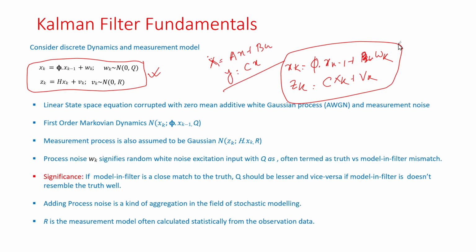If you have studied control systems, you know how to get the discrete equivalent from the continuous one. Anyway, when we start the target model we will explain it. There are some methods: one is called bilinear transformation, one is called Tustin transformation. Different transformation algorithms are there.